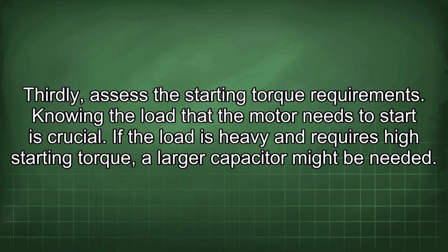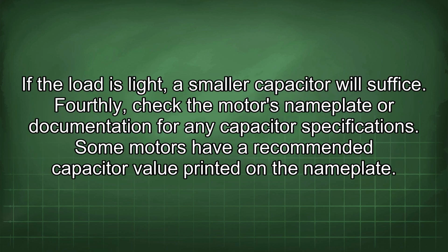Thirdly, assess the starting torque requirements. Knowing the load that the motor needs to start is crucial. If the load is heavy and requires high starting torque, a larger capacitor might be needed. If the load is light, a smaller capacitor will suffice.